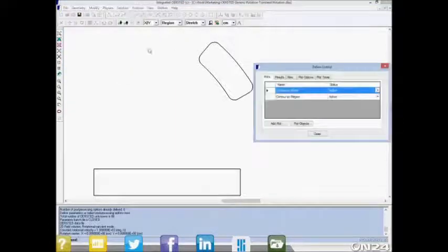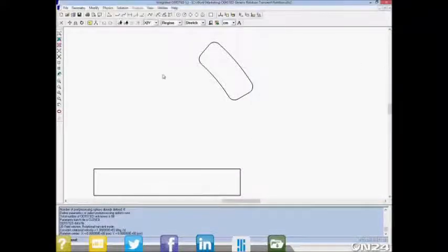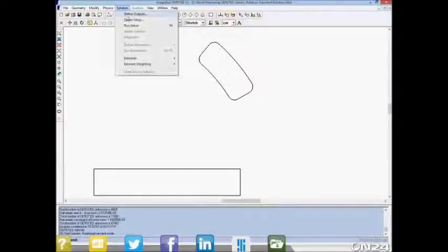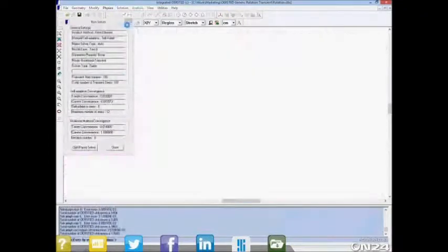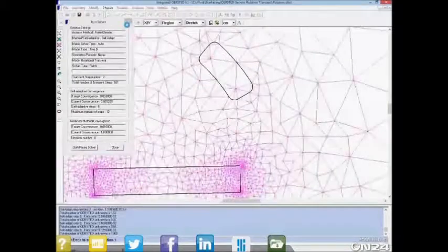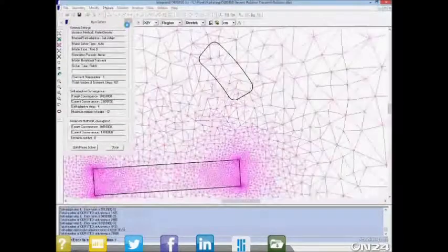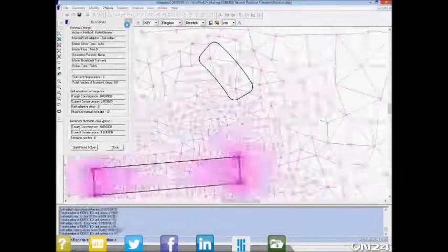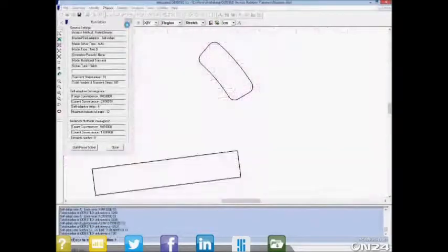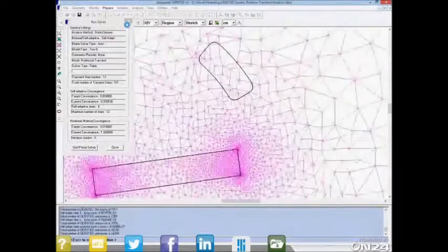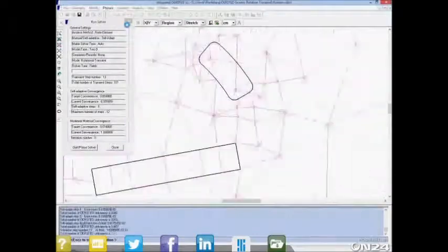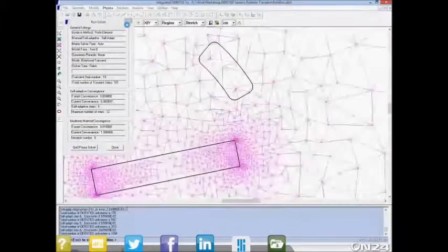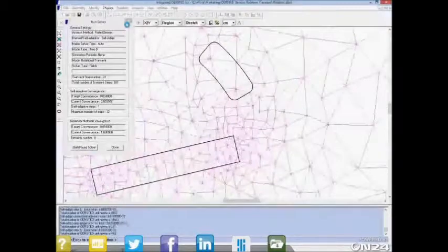In the output definitions, you can see that a couple of contour plots have been requested. One related to the magnetic flux lines, one related to the induced current. And once the solver has run, you will see the effect of that. Now you may notice that while our default solver is the boundary elements and we use it for most problems where we can, the default solver for most transient setups is in fact finite elements.